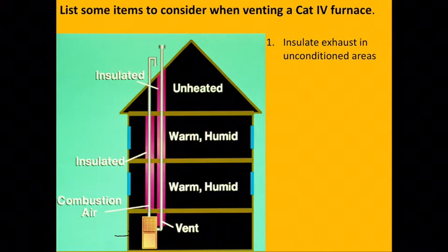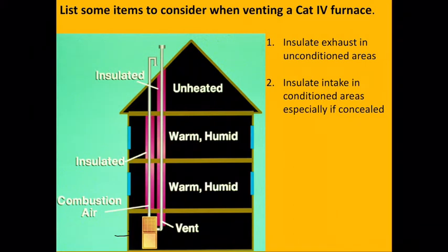Especially in an attic. If you are going to run a vent pipe in an attic, you have to insulate that pipe, or you're going to have problems where those gases could potentially freeze if you're in a colder climate. It probably would take temperatures of 10 degrees or less in most cases, but it certainly could happen in warmer than that even, but certainly below freezing.